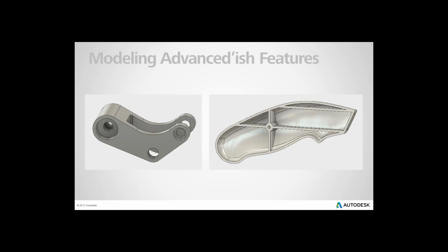So going on to today's stuff, this might take us a little while, so let's just keep moving forward. We can take a look at something like the combine command as well. But first we're going to look at our rocker assembly, taking that sketch to a solid, and different ways we can manipulate the geometry to make it a solid. That's just warming us up, reminding us how to do the modeling.